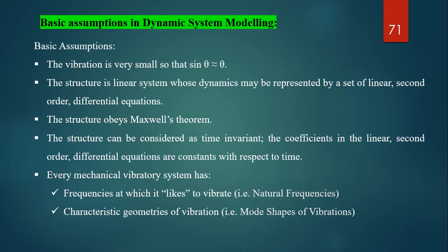The vibrating system is very small. It vibrates with a small amplitude, so that the sine theta function is approximated as theta, and the structure is a linear system whose dynamics may be represented by a set of linear second order differential equations.